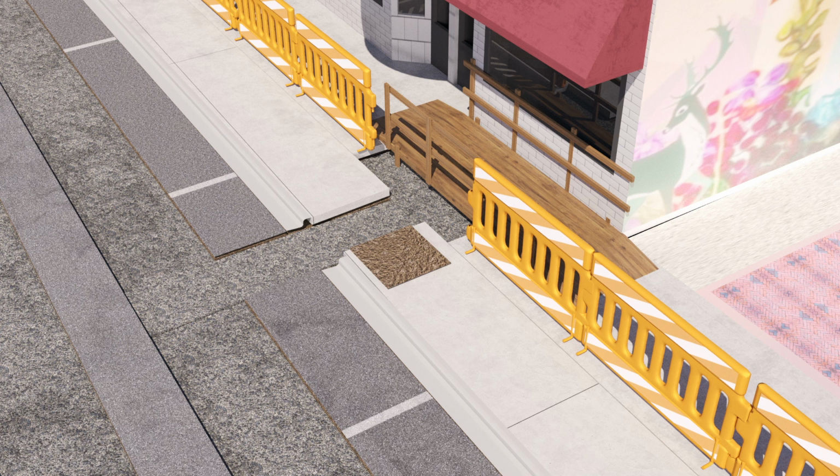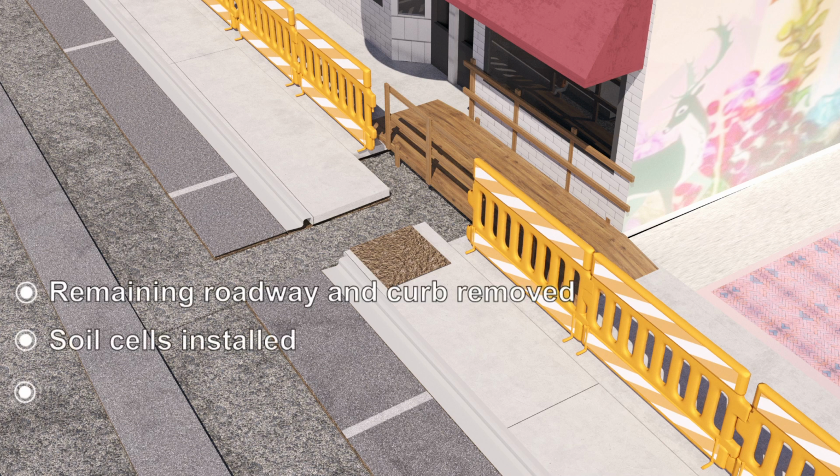Note that this example shows only the sanitary sewer installation for the building, when each building will also have a similar installation for the new water service line. The contractor may choose to combine some of these operations to take full advantage of each construction staging sequence. Next, the existing curb lines and roadway pavement are completely removed.